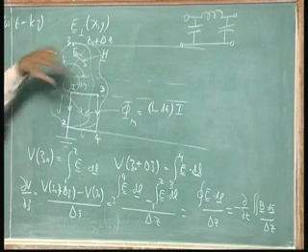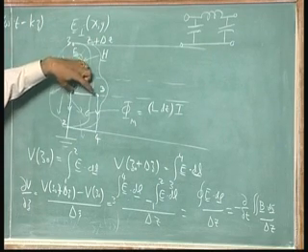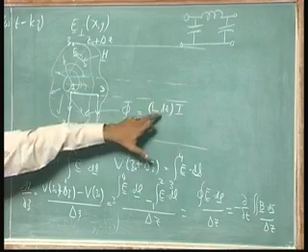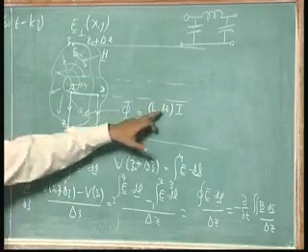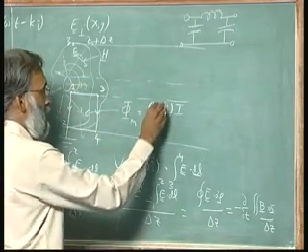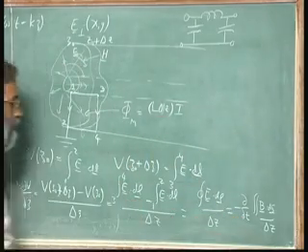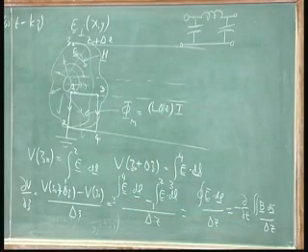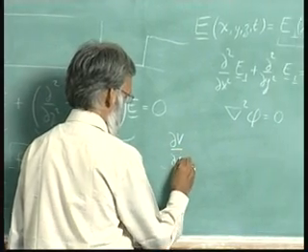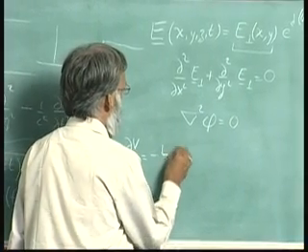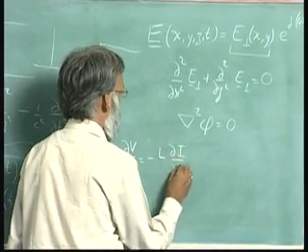It is not an inductance that is sitting in one point. So, the amount of inductance between z and z plus dz is L dz. So, I should write this as L delta z. So, the delta z cancels out, and what we are left with is the first equation, which is del v del z is equal to minus L del I del t.